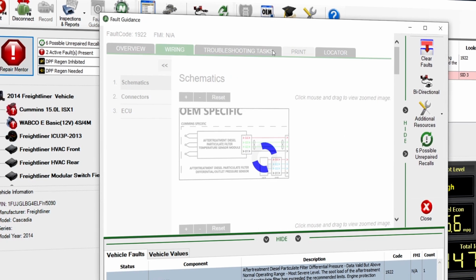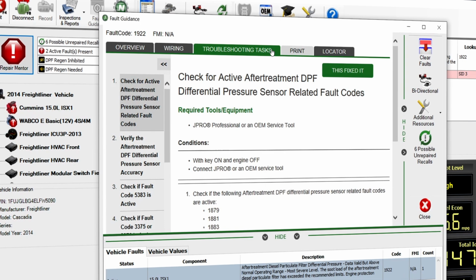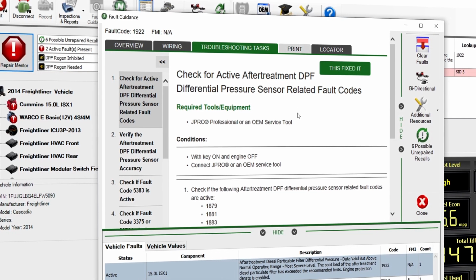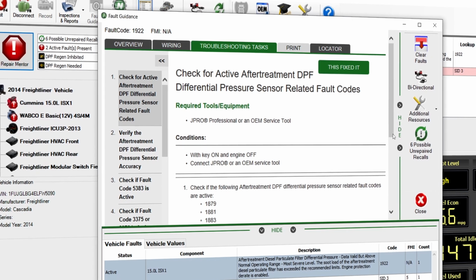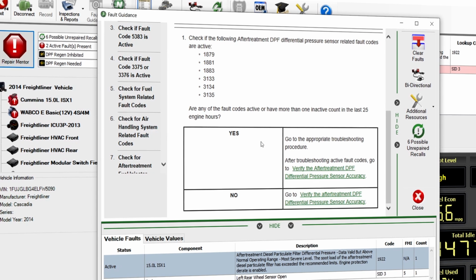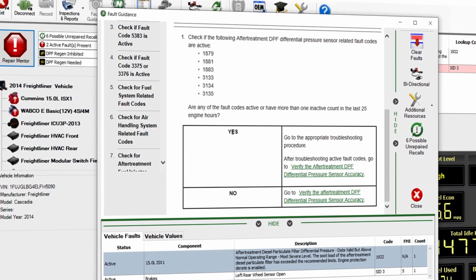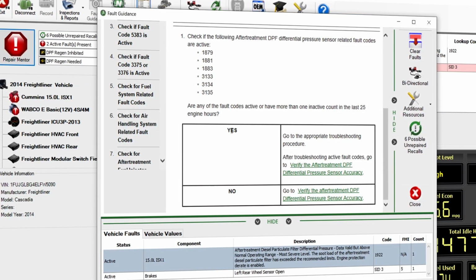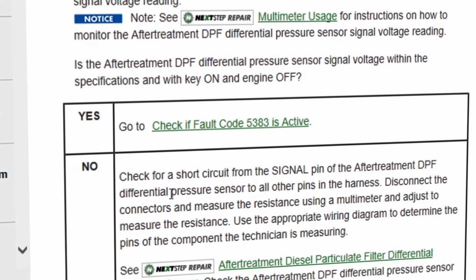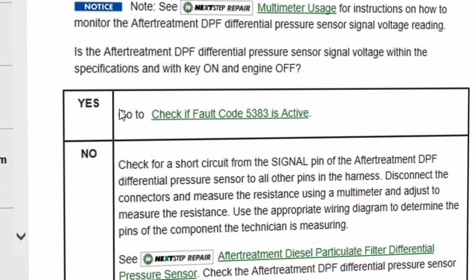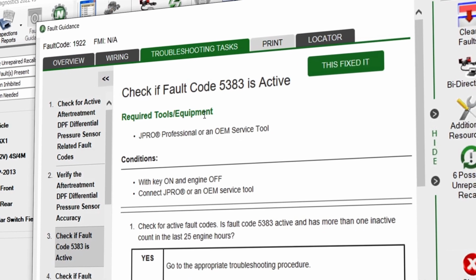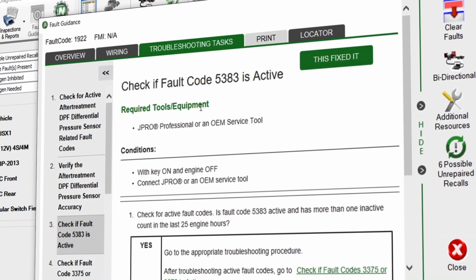Let's move on to the Troubleshooting tab. This tool lists items that need to be tested or inspected. When you click on this tab, it will alert you to the physical and electrical inspections to be performed. Follow the process on the screen. You will see a list of common troubleshooting procedures based on the fault you have selected. The screen will ask you yes or no to help verify the correct procedure. Each component will have a specific list of instructions to follow in terms of inspections.